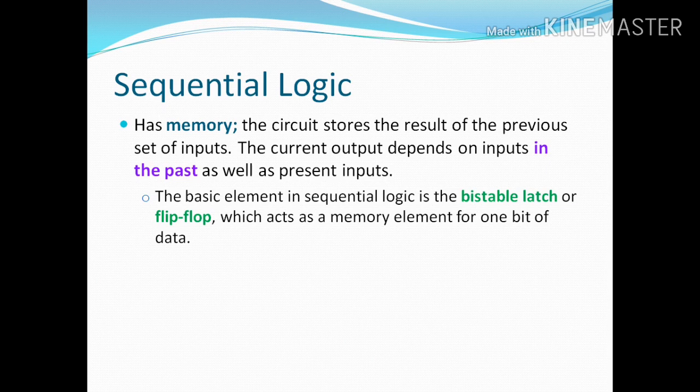Now, let's start the sequential logic. Sequential logic has memory. The circuit stores the result of the previous set of inputs in the current output. It depends on the input of the past as well as the present input. The basic element in sequential logic is the bistable latch or flip-flop, which acts as a memory element for 1 bit of data.